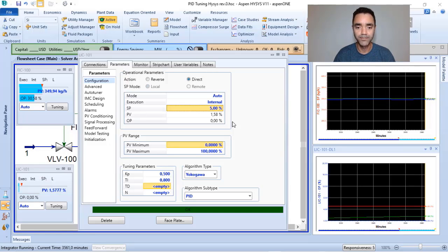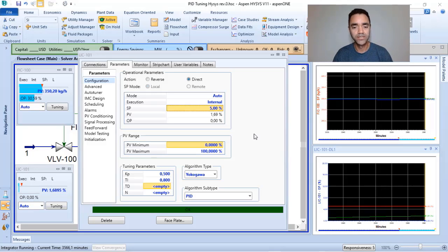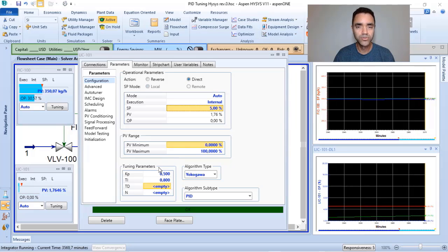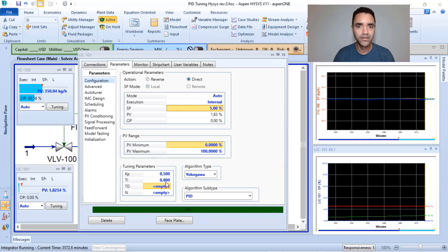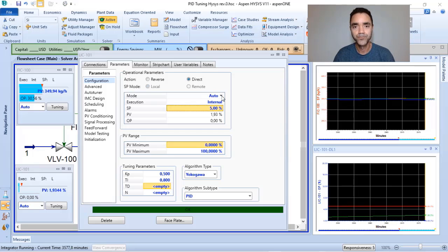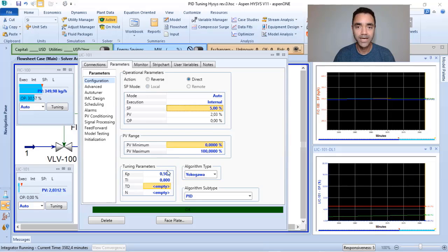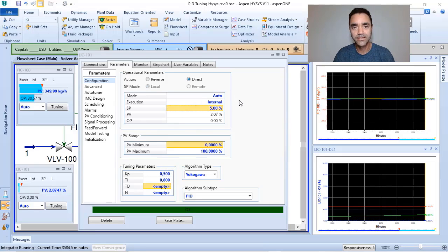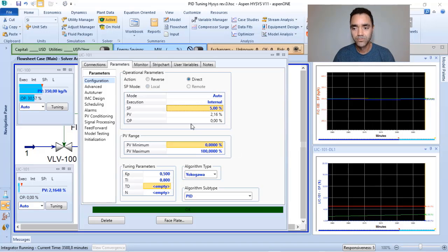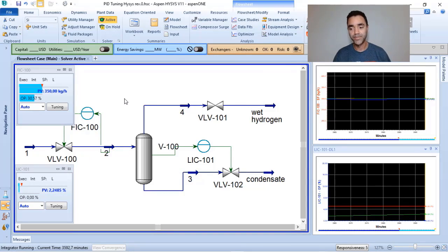So you have seen a bump there, but that's why it's interesting, when we are doing the PID, that most controllers ask that we put the controller in manual, do the changes in the KP, TI, and so on. And after that, we return to auto. So here, guys, we have the PID controller in Aspen Hysys.